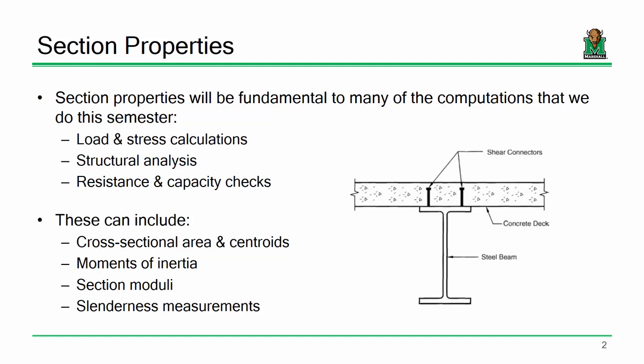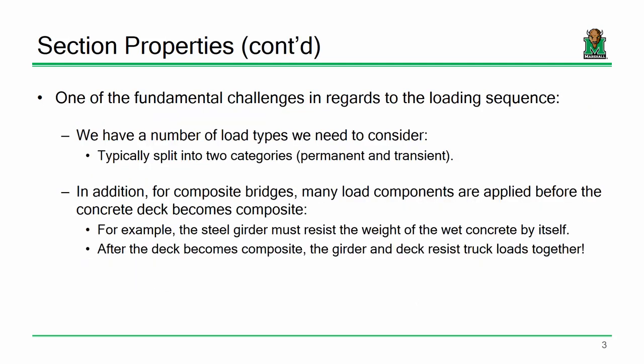That's what it means for it to be composite, that they're bending and behaving together. When I drive a truck over that bridge, it is not just the steel beam by itself resisting the load of that truck. No, it's the steel beam and the concrete acting together. You see what I mean? So we have different sections that are going to matter.